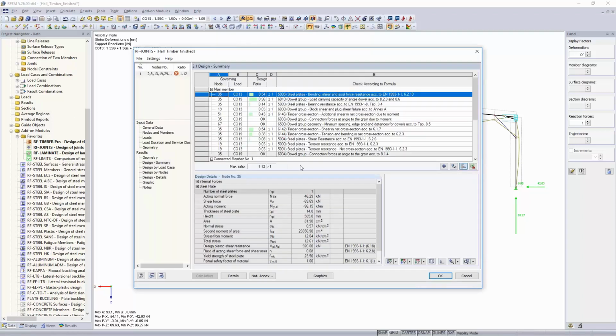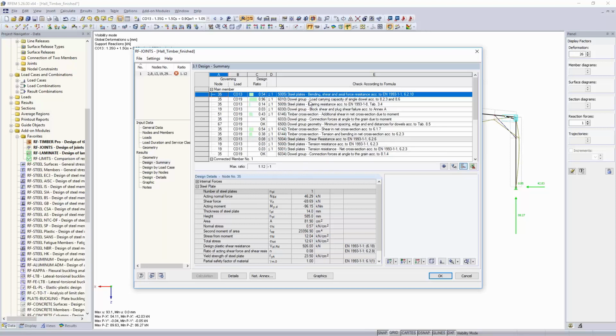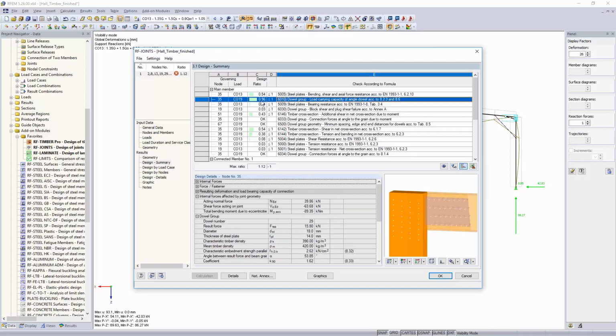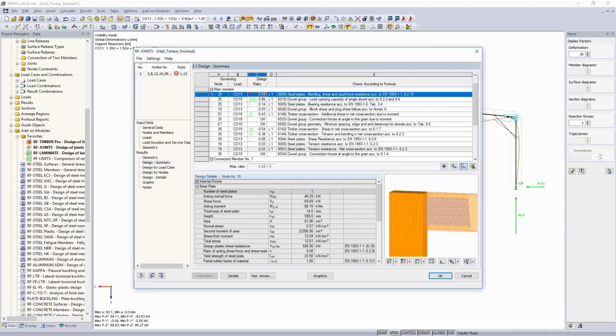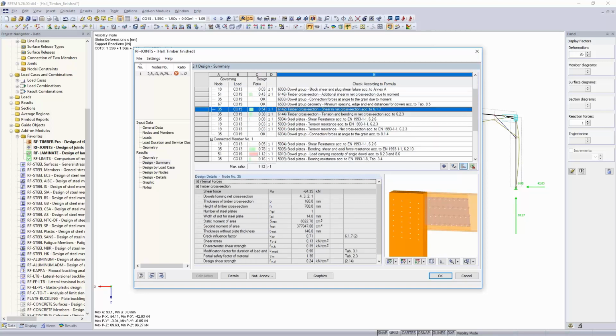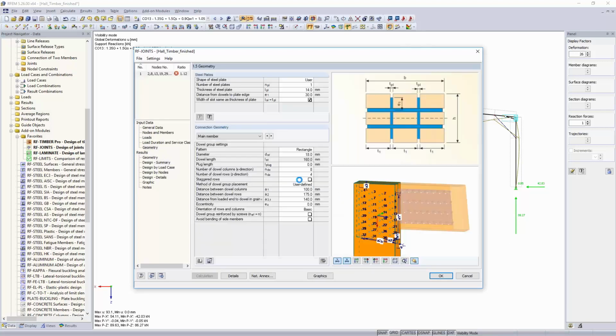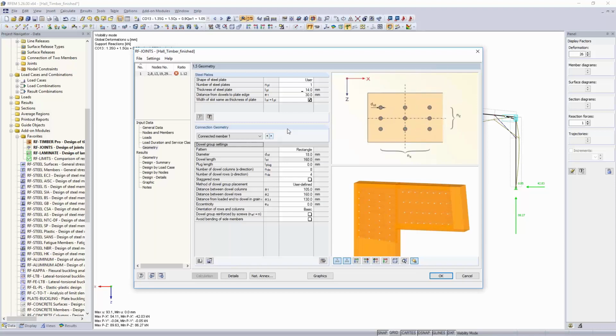So, and you see now we have an overloading of 12%. Damn, that's actually not what I wanted, but let's have a deeper look into it. So the dowels are now loaded nearly 50% more. Steel plates also loaded pretty much more, but the timber is now not a problem anymore, but here the connection is a problem. Okay, what else can you do if you do not want to change the geometry? The main member was actually okay.